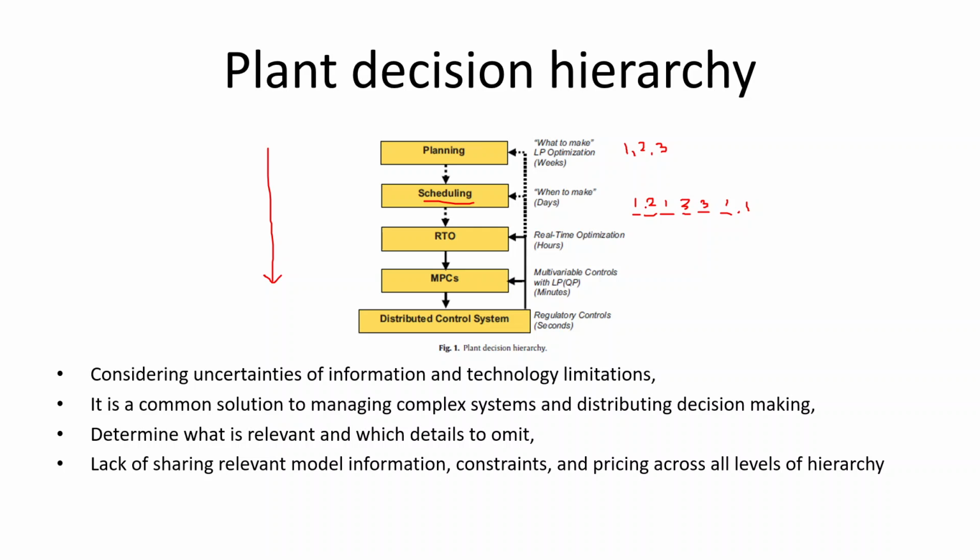And then they know which crude is coming in and which product they should make, and it goes to what they call RTO, real-time optimization. In this RTO, they have a plant model, like the one I showed you in the Excel. They have a plant model using that EO type of approach to give a direction on what are the set points that we have to put into the plant, into the operating conditions, right?